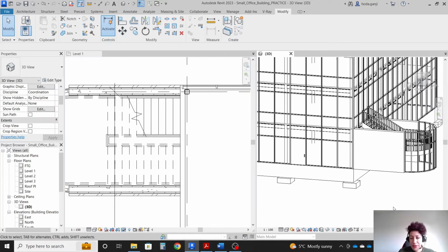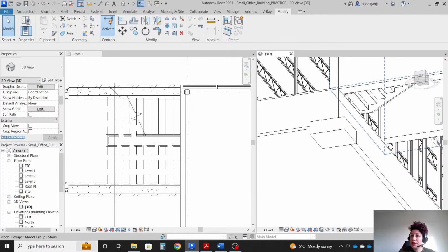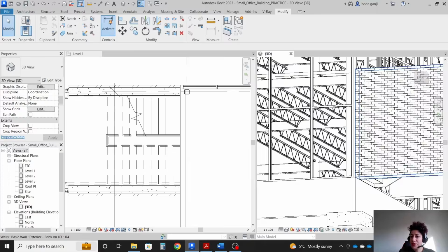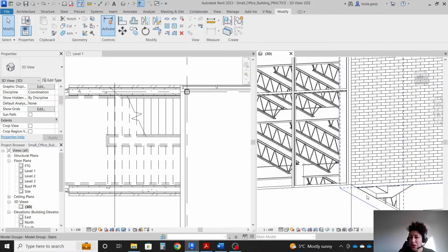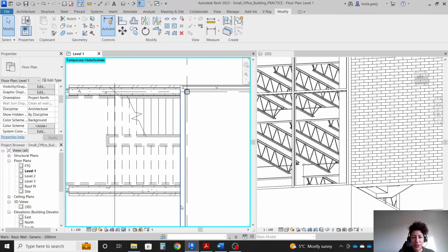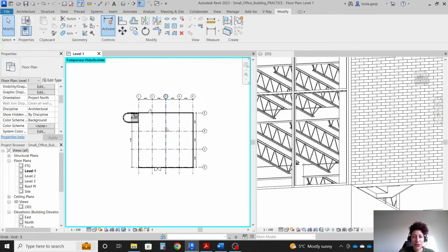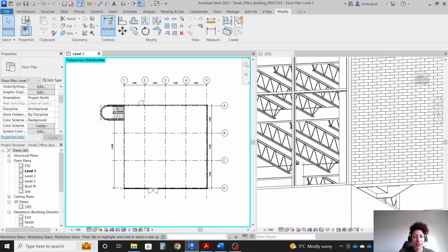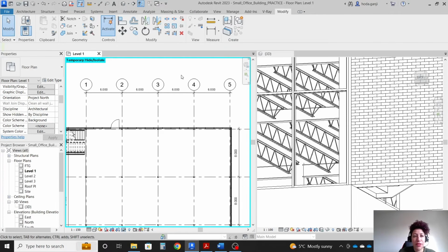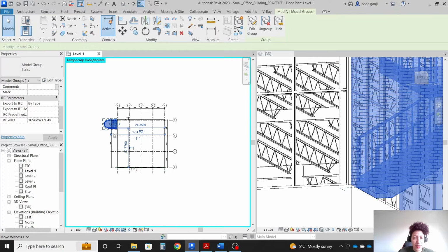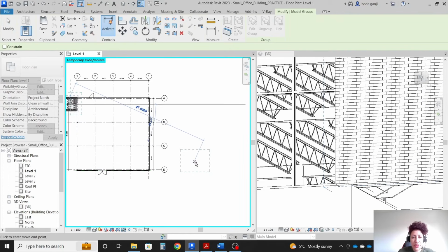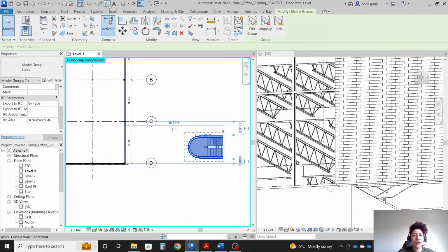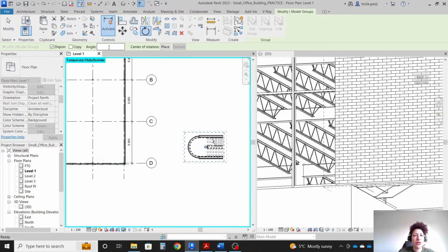Later, we need a little bit of a piece of floor to cover that gap over there, because if I go with HH here again, you see that the floor starts there. But that's good. I also need these stairs on the other side of the building. So I'm gonna select this, Control C, Control V again, and let's rotate this, a new one, 180 degrees.